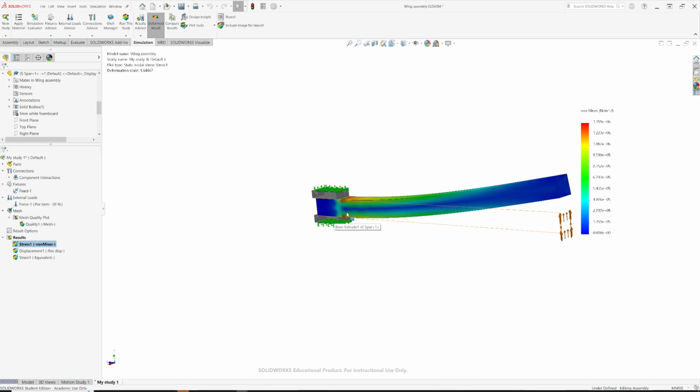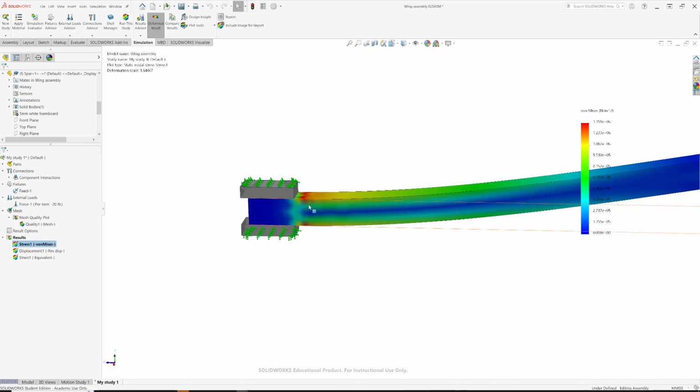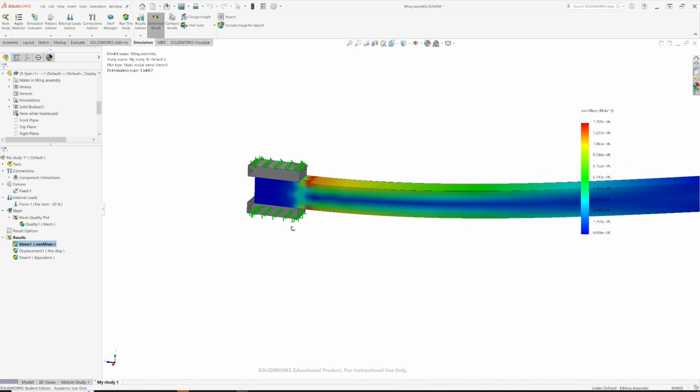because that's where the bending moment is largest. The other thing of significance is that the peak stress is at the top and the bottom of the beam, and this comes down to the way stress is distributed. If we're pushing up this way, the top bit's in compression, the bottom bit's in tension, and the middle of the beam's under no stress whatsoever. It's what's called the neutral axis of the beam in the middle. The stress is 0, and the stress peaks at either side. So if your beam's going to fail, in this sense, it's going to fail by crushing up here and splitting underneath there.